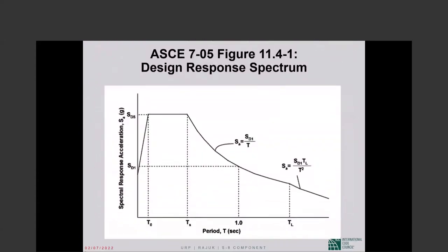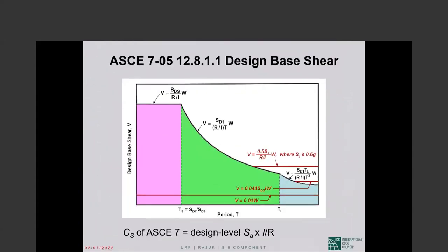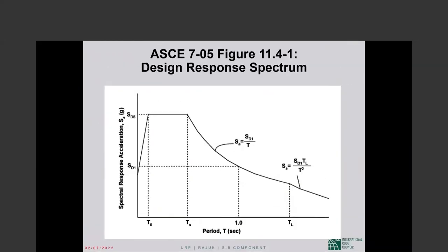Yeah, anyhow. Okay, the design response spectrum of ASCE 7 you have seen 10 times by now. The reason I showed you again is that when we do the equivalent lateral force procedure, we modify the elastic response spectrum. This is the elastic design response spectrum of ASCE 7. Design level, elastic spectrum.